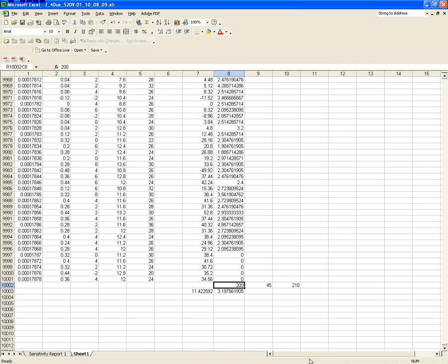And I don't know what the inductive impedance is really, because that 209 ohms that I came up with, for a total of 219, was based on the frequency of the pulse itself, which is much higher than the rest of the frequency throughout the time period. So the inductive impedance is always changing, and those changes themselves affect how the circuit alters this phase angle.